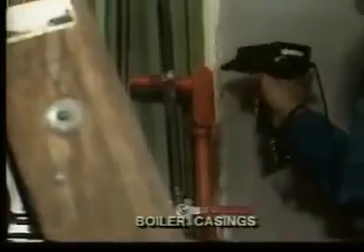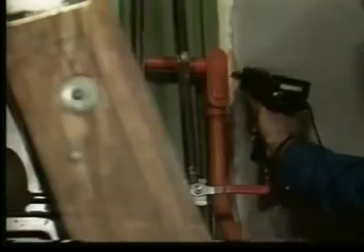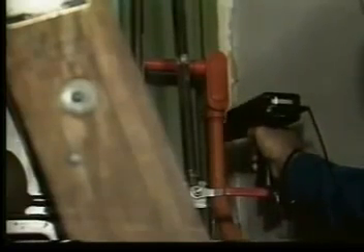Boiler casings are tested using the ultraprobe scanning module in the fixed band. Scan the casing itself at a set distance. Listen. Sometimes you may need to use the rubber probe. Adjust for background noise which may interfere.